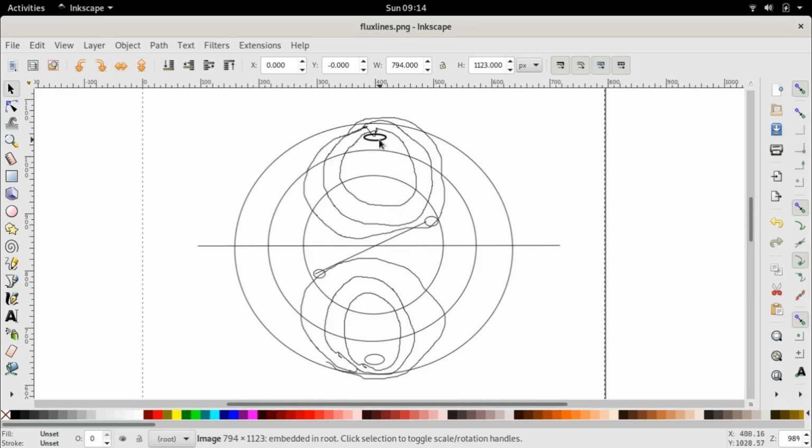So therefore we concluded that the self-inductance of the stator is almost independent of the rotor. Again, I say almost independent because there will be some non-regularities. For example, even if it's a squirrel cage induction rotor, there will be bars, and as it rotates, these bars will cause a change in the reluctance of the flux path. But this change is minute because we are talking about only a very small change in the reluctance. So you could say it's almost independent.